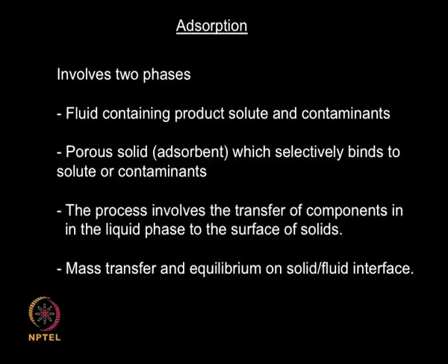So each solid has a certain capacity beyond which it cannot adsorb the contaminant or the solute, number 1, and number 2, the mass transfer determines the rate of adsorption. So the mass transfer determines how fast or how slow the adsorption process is, and the equilibrium concentration determines how much I can adsorb.